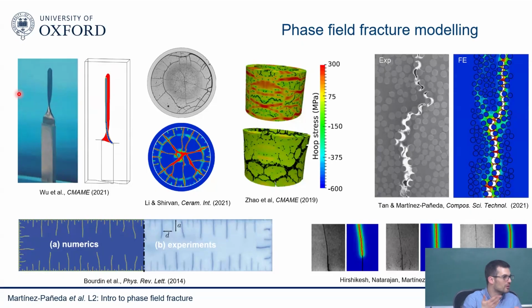But yes, you can capture, in principle, what fracture mechanics people will call the maximum energy release rate criterion, right? So cracks will take any trajectory they feel will minimize the energy, any trajectory that they feel is more energetically convenient, which is in agreement with what we see in experiments. And what I want to clarify is that when I used to work with other methods, when this crack reached this crack, I had to make a decision on what to do here. Here I just have a uniform mesh, fine everywhere. My cracks decide what to do by themselves, just based on that energy balance, energy principle.